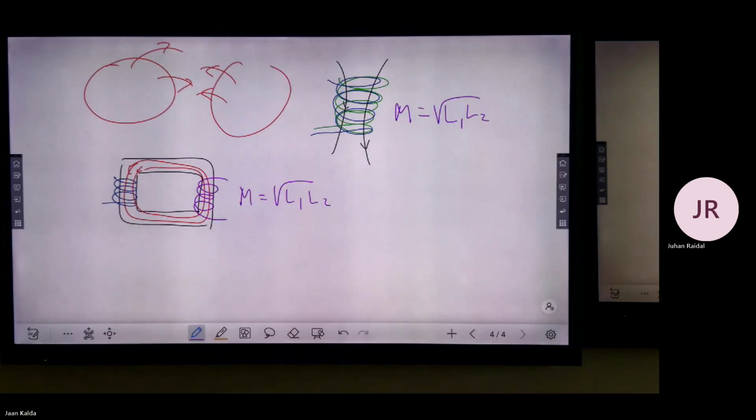Now, one more fun fact is that sometimes you use the first solenoid, without a ferromagnetic core as well, as a transformer. When you might want to use the transformer without a core, what do you think? Space issues? Because you have dissipation due to Foucault currents, and possibly more importantly, you have non-linearity.